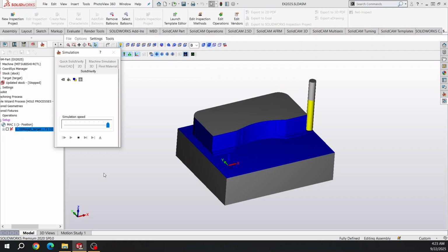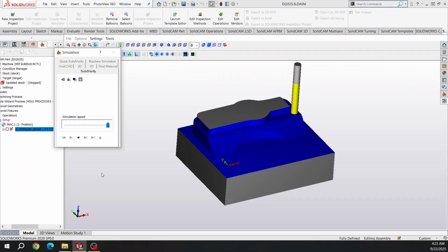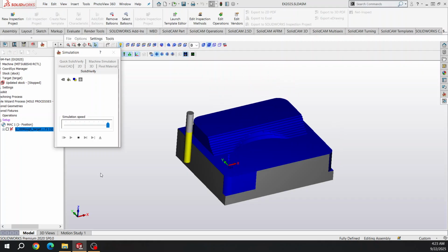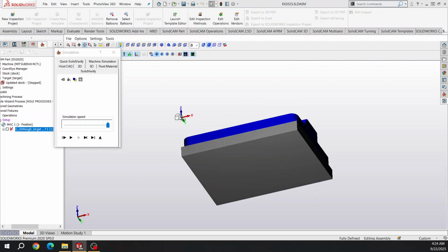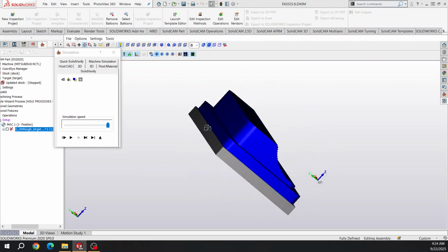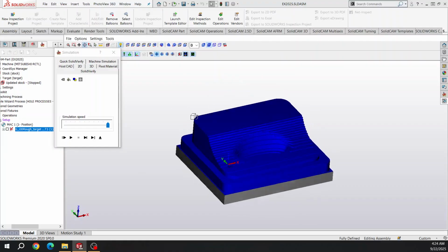But this is a one-step operation; you don't need to do one at a time. It automatically identifies what material needs to be removed, and removes everything within the given constraint. Remember we set the levels from 0 to 10 to -50, so within that level it's going to remove all the rest material. In one step you get the part ready for finishing operation.